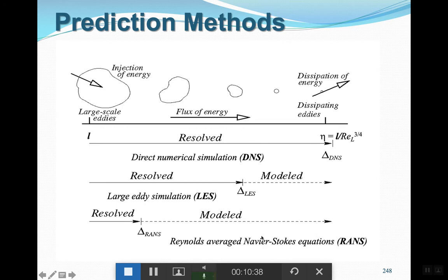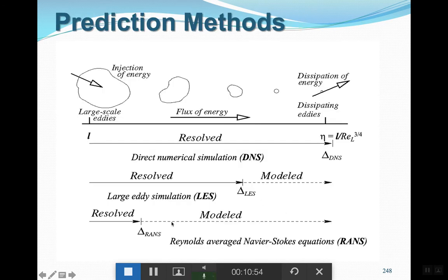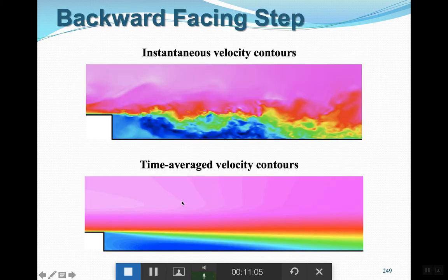So when we say we are using a RANS model, you got to remember, okay, we are basically just solving the large eddies. The others are being modeled. Okay, so remember that. Now, since in this class we're gonna focus on RANS models, and to be honest, 99% of the problems in industry are being solved with RANS models, we're gonna focus on that. If you remember, in RANS models, I said you are taking time averaged velocities, meaning you're solving it all together as a steady flow.